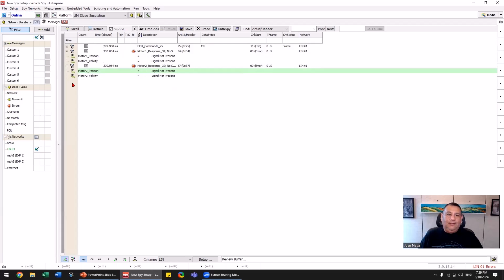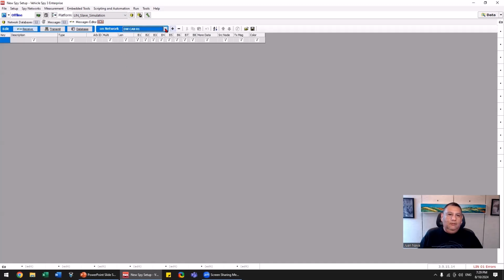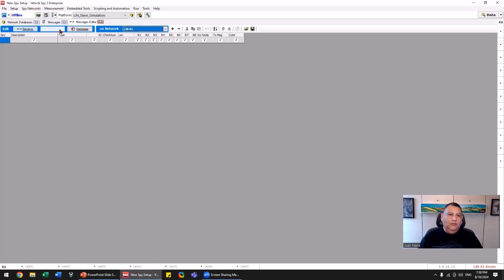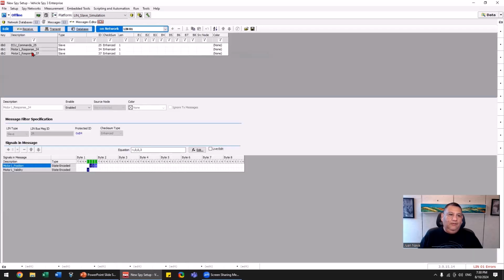In order to fix that, I'm going to stop Vehicle Spy. I'm going to go Spy Networks, Messages Editor. I'm going to go into LIN, and click Database. And then these two messages, I'm going to copy over to transmit. Now, if I'm only responsible for one of these modules, I will only copy the one that I care about. I wouldn't copy all of them, but in this case, I'm going to simulate both of them. And now I'm going to go to transmit. Now I see both of them.